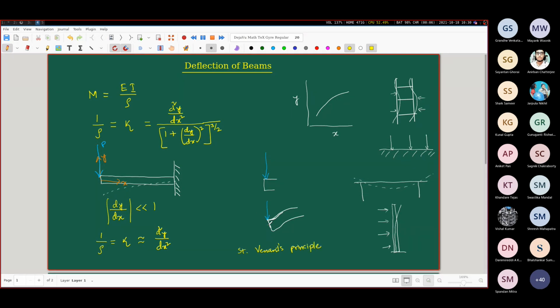Okay, so the actual nature of the loads specifically at the point of the loading is going to be significantly different than what is predicted by these kinds of undergraduate level theories. Yes, sir, I understand. So even when there is a uniform distribution load, then this will happen, or it will not happen? So uniform distribution of load doesn't have this problem. Okay, it is only in the case of point loads then that you have this problem.